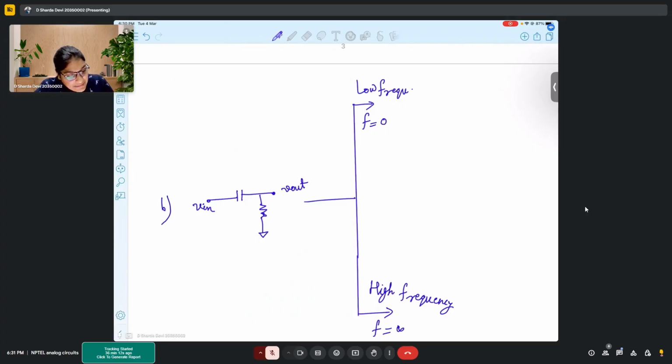So if my capacitor becomes an open circuit, and here I have a resistor R, this is V out. So if this is the situation, what is my V out then? There is no path between input and output voltage, correct? Since it is an open circuit, there is a break over there. So if there is no path, then V out would be 0, correct?